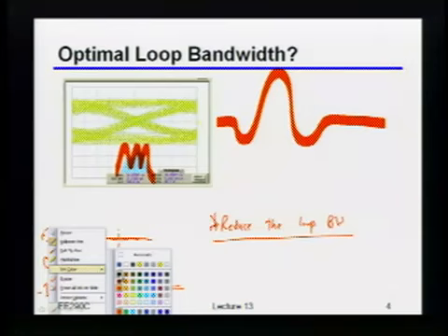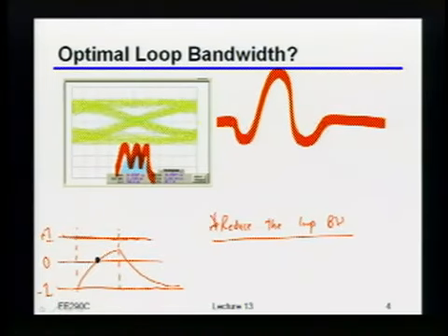Notice the point at which I cross 0 here and the point at which I cross 0 there, relative to my bit positions, is moving all over the place. In this one here, it may cross around the center point, but maybe not quite. It could even be shifted to be a little bit late. But notice over here, because I didn't make it all the way up, I'm crossing 0 much earlier. So even if I could build the CDR that Igor just said is impossible to build, it actually wouldn't help me.